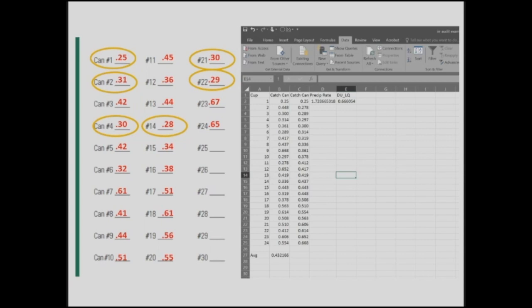But this is essentially what we're going to do. So from that system of 1.72 inches per hour, we want to put a half inch out. It's going to take us 17 minutes, okay? If our system was putting out maybe about, say, 3/4 of an inch an hour, what would we have to do to change our runtime? Yeah, it would be about double the runtime because it's about half of the precip rate, okay? So hopefully that makes sense. Certainly we'll go through some more. If you guys have questions, we can try to do some more back and forth and pull up that formula from earlier.